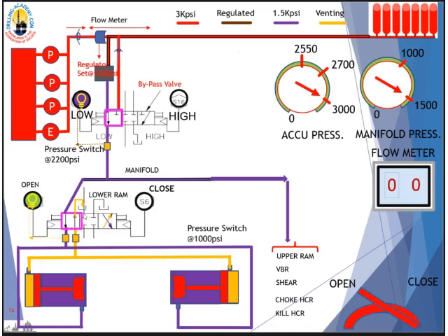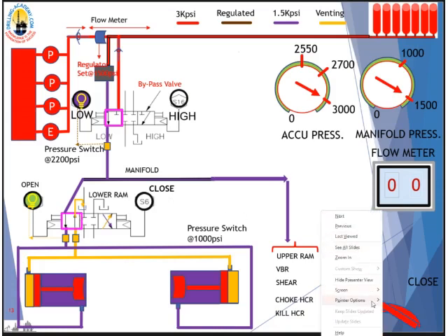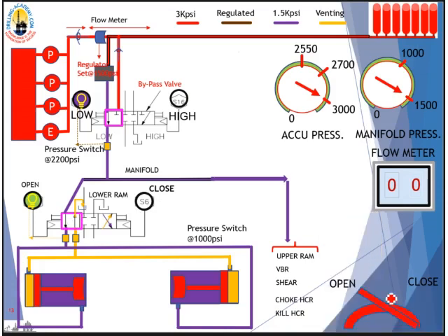All right, so now when we press close, the same thing will happen here. The air will be acting on this side and it will pull the valve sleeve from open to closed position. Fluid will be fed to this line and comes down to the opening chamber, comes down to opening lines in here.